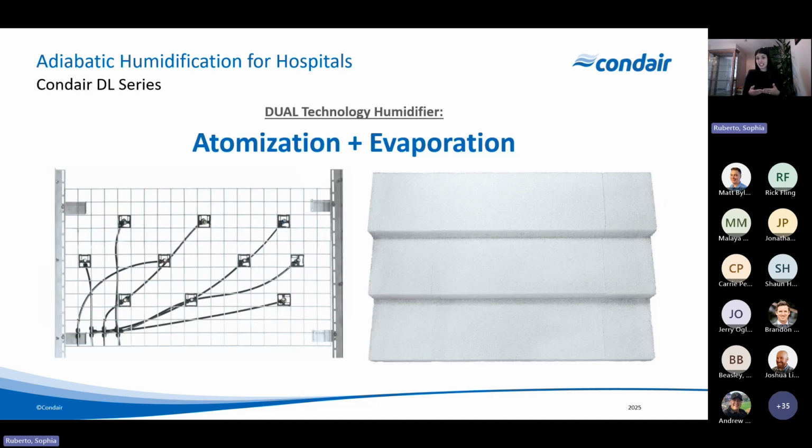And then we have our third technology, which we'll be focusing on today. And this is what combines the two principles, atomization and evaporation. But the key difference here being that instead of a padded media, we use a ceramic media. So it's not absorbing any water. The water would sit on the surface and then evaporate. So to help with that hygiene level.